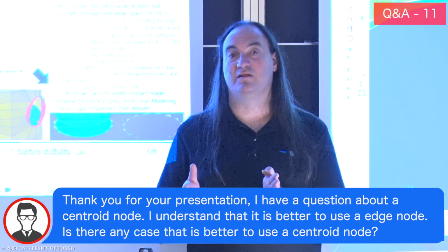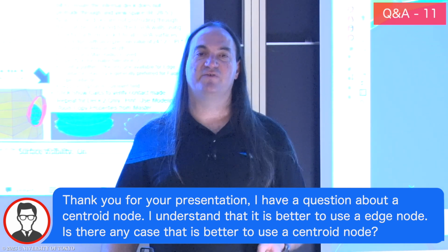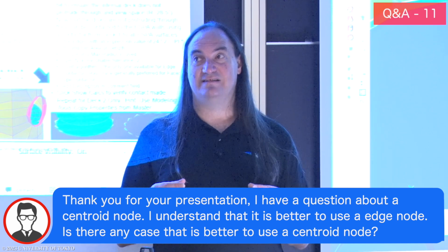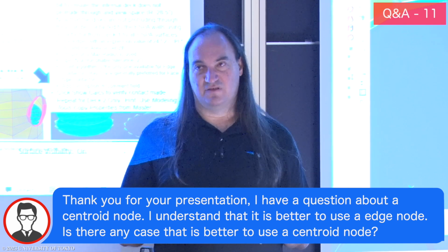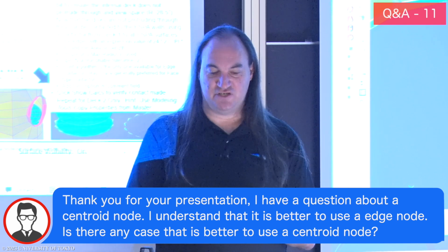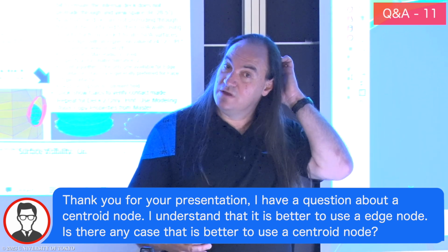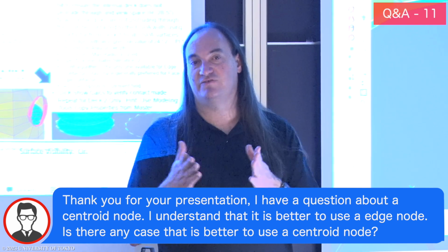It just might mean a little more work for you to connect one centroid to another that are on different surfaces. The edge nodes really are a finite difference 1D approach that's very similar to centroid. It just changes the lengths and the cross-sectional areas through which the heat flows to the locations where the nodes are along the edges rather than at the centroid.